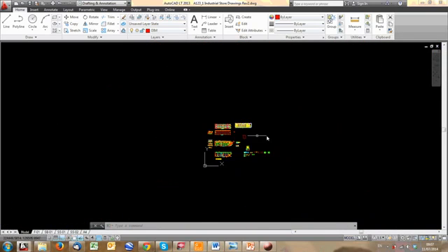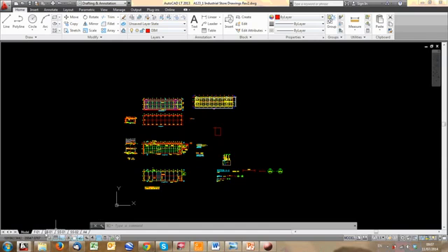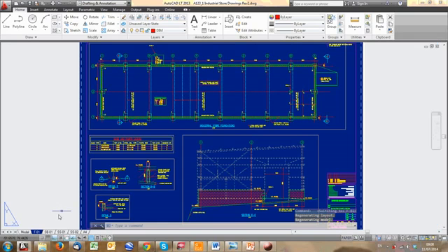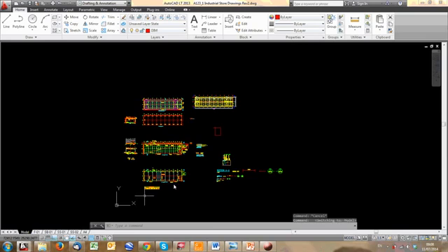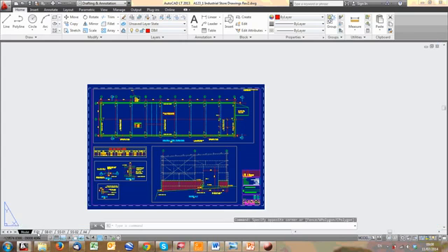Though this is model space, as I said, it goes off in every direction for infinity. But if you want to look into the space and create a drawing, which you can print or PDF or whatever you want to do with it, you need to go into paper space. These tabs are for paper space, and I've set it up that this is the name of the drawing. It's Foundation F01, my first foundation drawing, and this is now a piece of paper. You're looking at an A1 drawing with windows into model space. So from model, you set up a window around, so I will see what's in that box right now. But you create those windows from paper space.